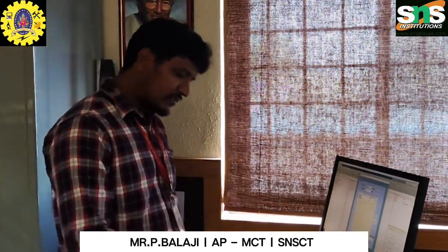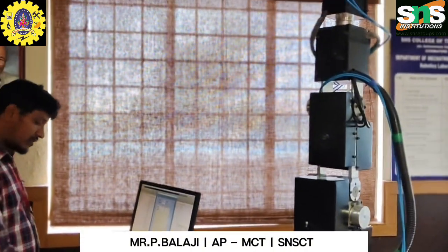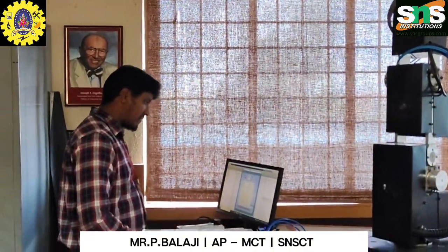And then if you want to control the second axis also, you have to select the second axis and give a value below 90. I'm going to give a value of 40 degrees, and add it here. And then for the third axis, it may be 20 degrees, so I'm going to give 20 degrees. For axis 4, I could give up to 320 degrees because we can control it for the entire 360 degrees, but I'm going to give 60.